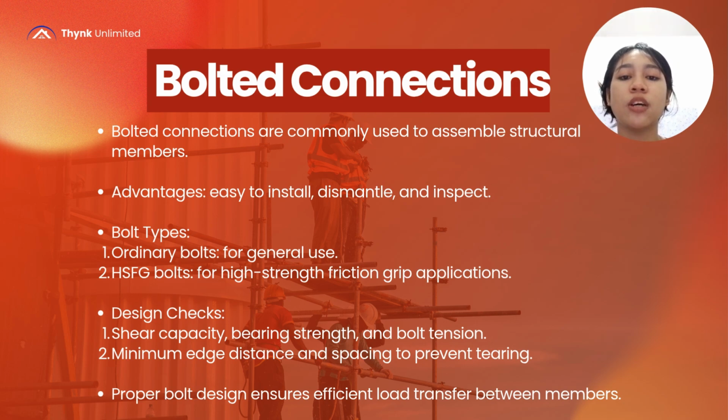For the design check, we check shear capacity, bearing strength, and bolt tension to ensure the bolt can safely carry the load. Number two, we also check the minimum edge distance and spacing so the plate doesn't tear or fail around the bolt. Overall, proper bolt design ensures efficient load transfer and safe performance.